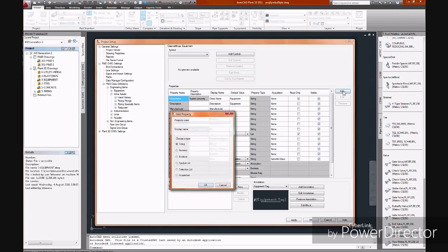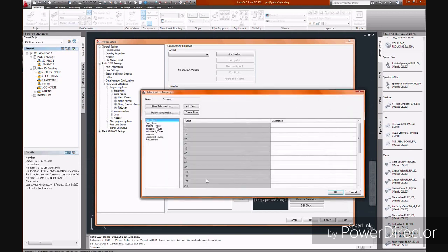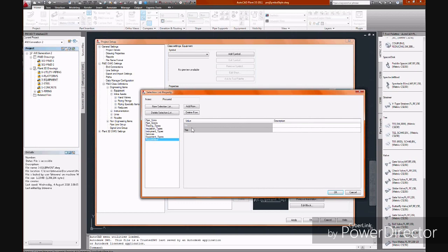So open up Project Setup, navigate to our hand inline items hand valve class, click the Add Field button, name the field, make it a list field, and the two values in the list will be yes and no. Preset default will be no.